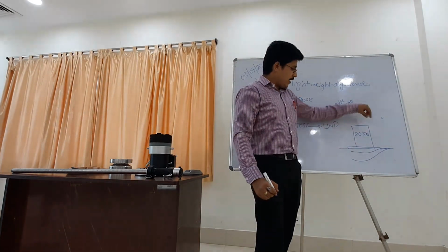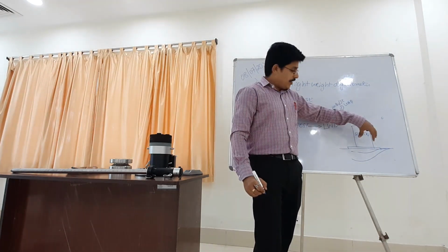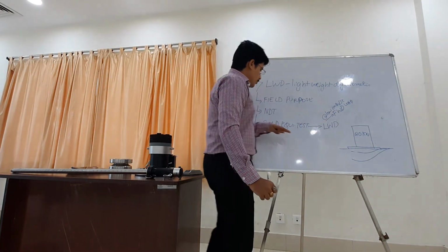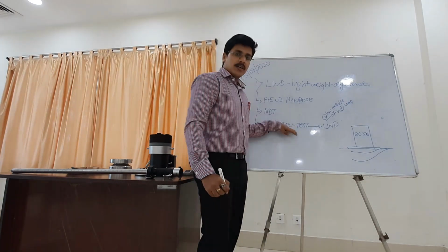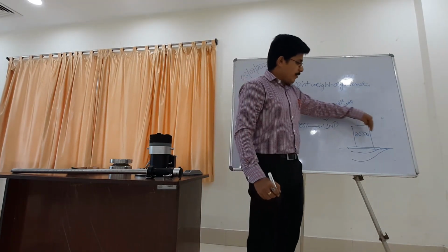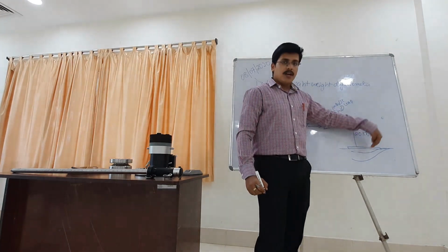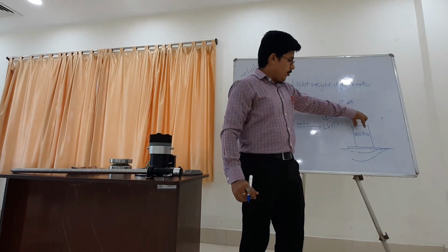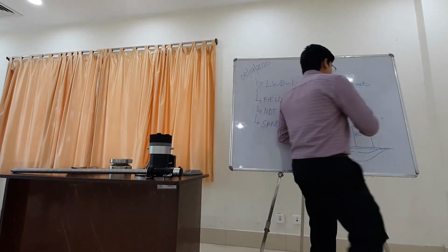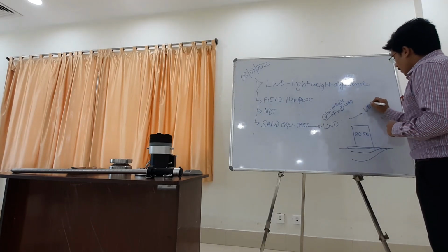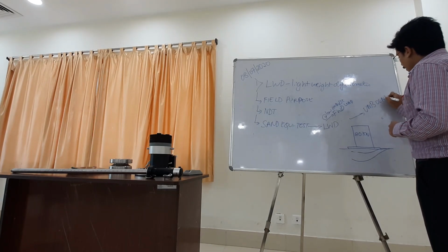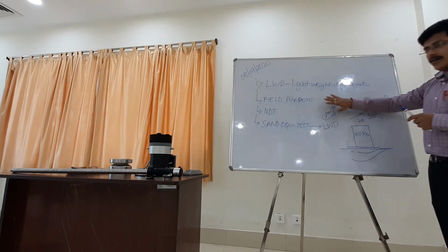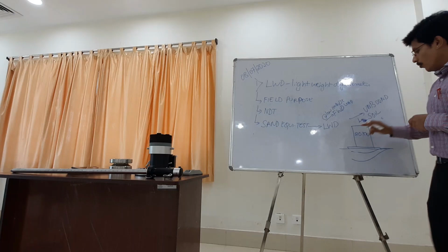So this way you can identify the quality of compaction or degree of compaction while constructing the subgrade at very close intervals. So no need to do sand equivalent test at very close intervals. We can go for LWD so that we can measure the modulus and also the deflection and see the quality of construction at the site. But due to low load as 20 kN, this is very applicable for unbound granular layers and soil. So LWD cannot be used for concrete or asphalt pavement because of the load, right?